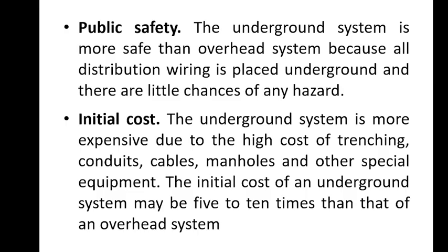From a safety perspective, underground systems are generally more secure because all electrical conductors are buried below the ground, significantly reducing the risk of electrical contact, electrical faults, and hazard to the public. However, these advantages come with a major drawback in terms of cost.